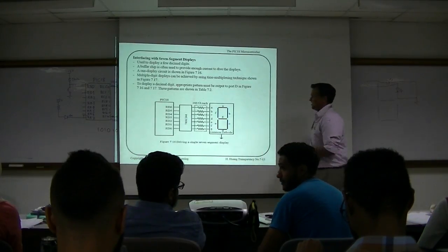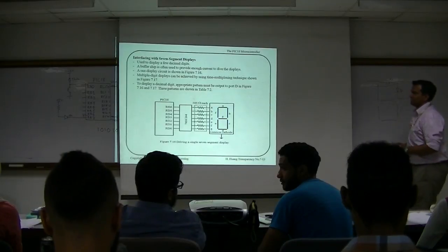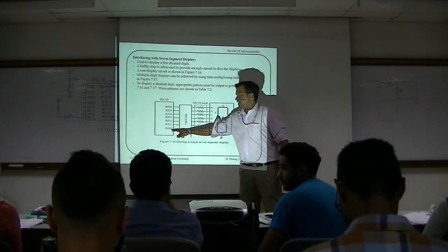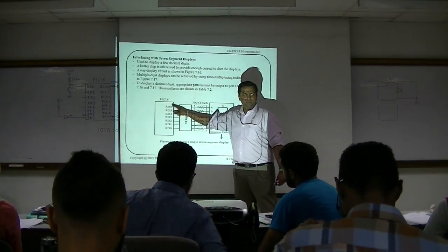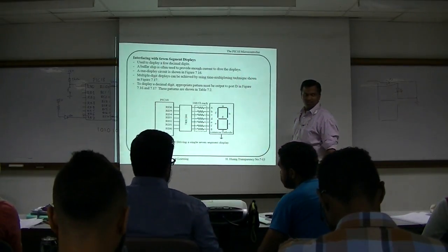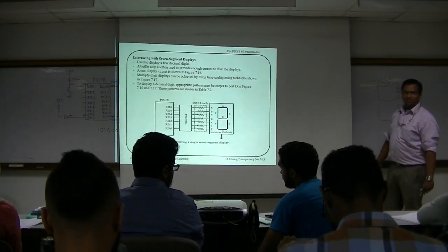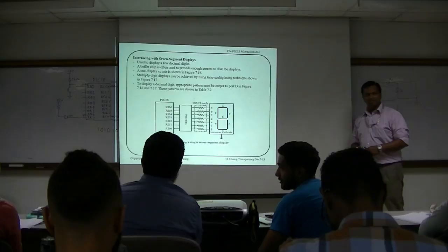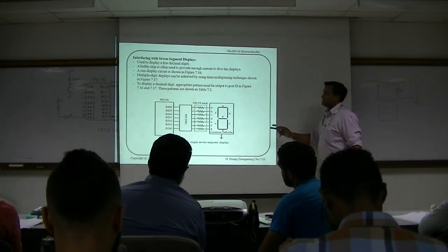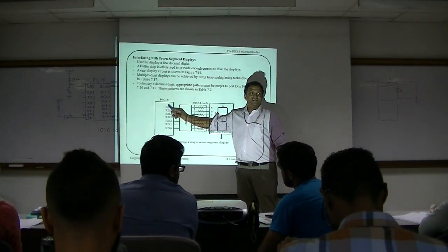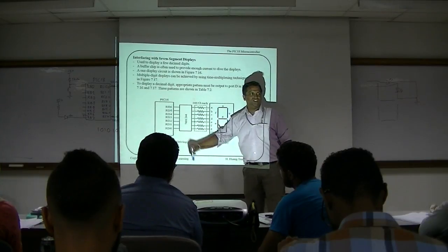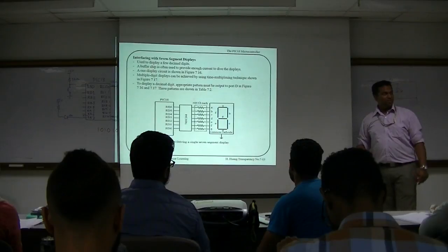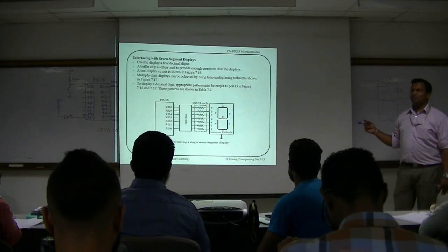Because here is 0 to 6, that is 6, which is the MSB. This is the LSB. This is the MSB. 7E. This is bit number 6. That's RD7, which is not being used. The RD7 is not being used, so by default just keep it at 0.